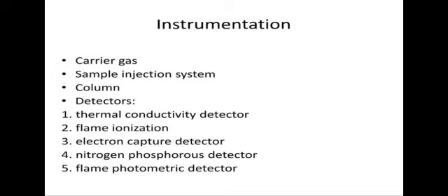Next, detectors. There are various detectors used in gas chromatography. Gas chromatography employs a wide range of detectors, of which the flame ionization detector and thermal conductivity detector are the most common ones. Thermal conductivity detectors, briefly: these detectors utilize a heated filament placed in the emerging stream.